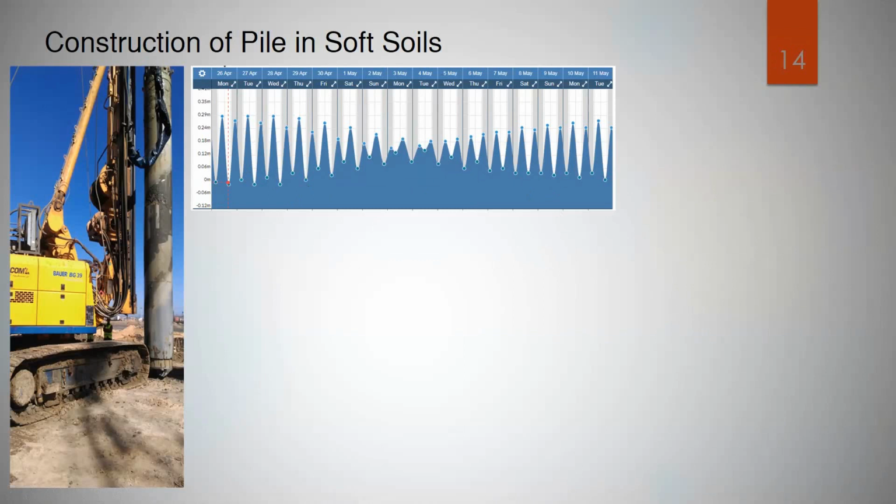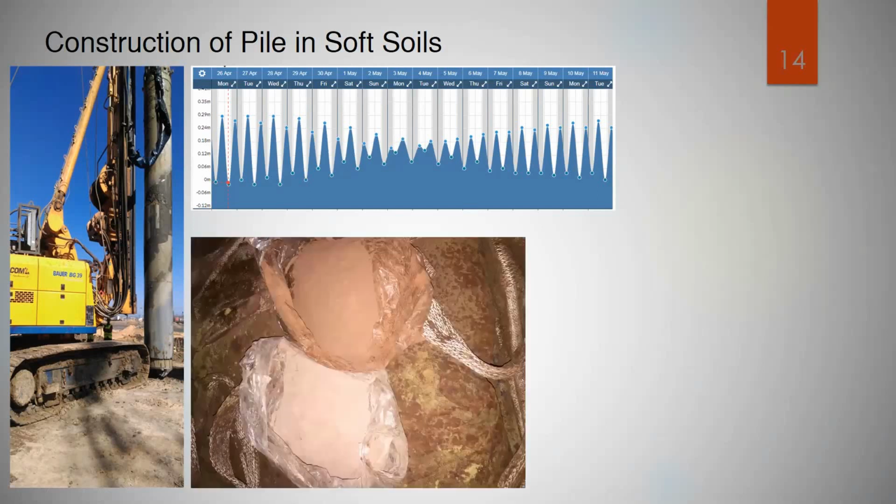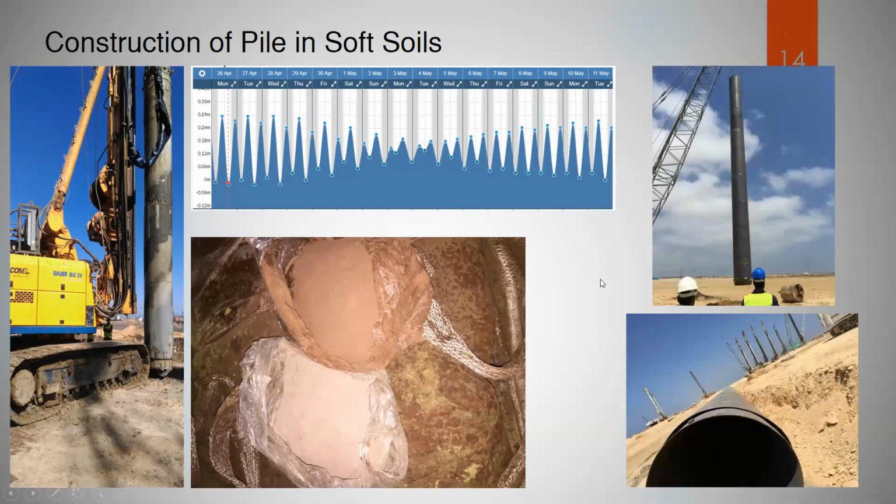We have to first start with the perimeter piles, then go inside to make like a wall to minimize the water movement effect. Also, we make trench stability for the pile. We had to use barite to increase the density of the drilling fluid to make more stabilization for the pile during construction. Also, in the non-working compression tests, we use a double sleeve.